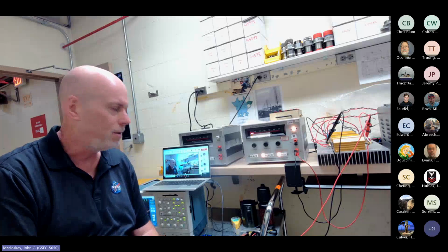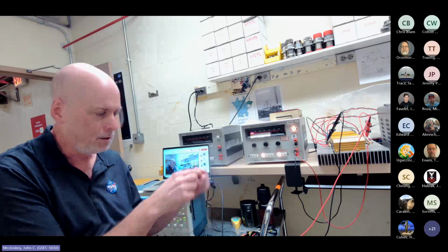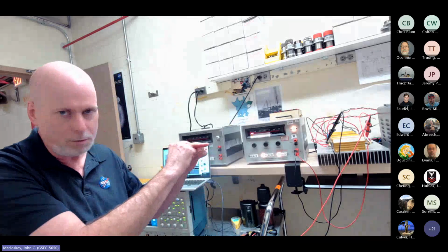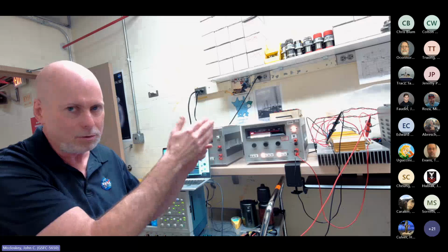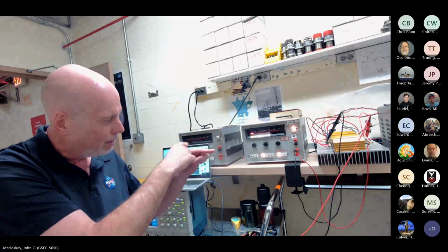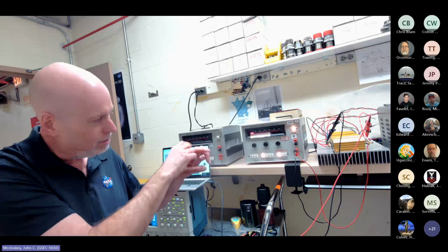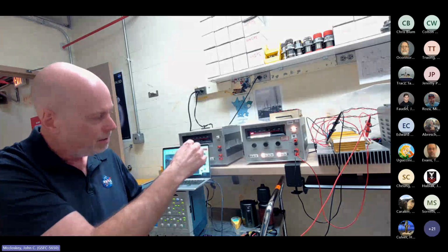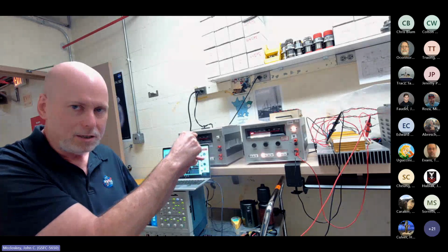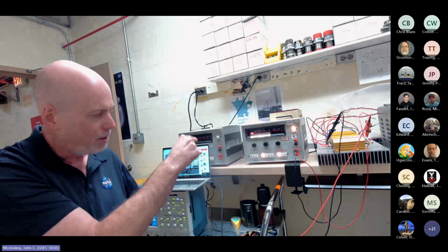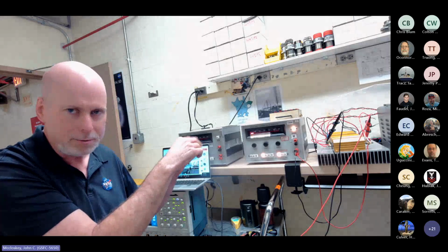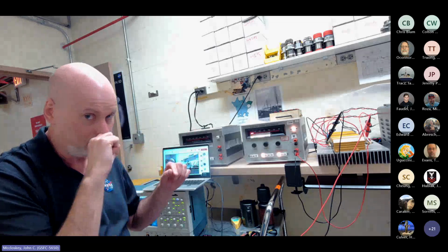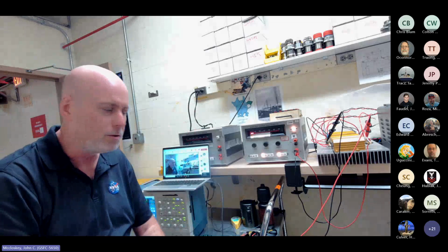I'll start with the turn off transients. I set the scope to trigger, like you have your 30 volt line, right? When you're fully up and running, the power bus is giving you your 30 volts, give or take. And we would put a DC offset on the scope and expand around it, set the trigger as low as we could above that 30 volt line with the noise riding on top of it without getting spurious triggers. So maybe a few tenths of a volt above the 30 volts.